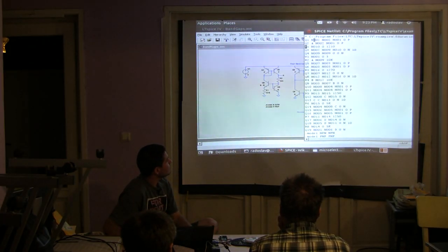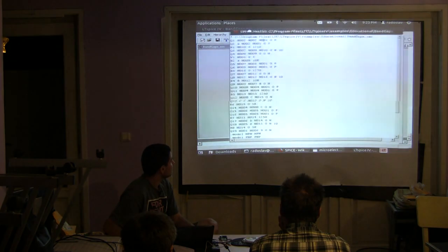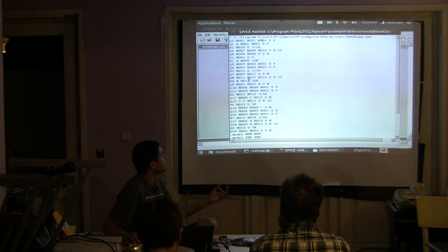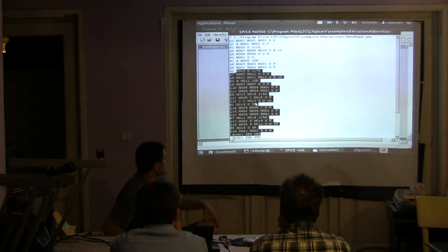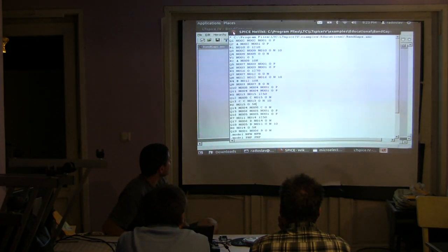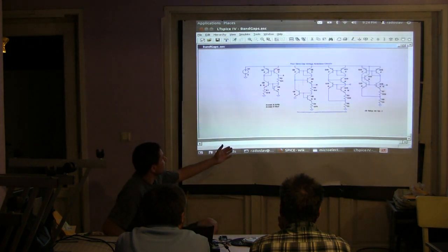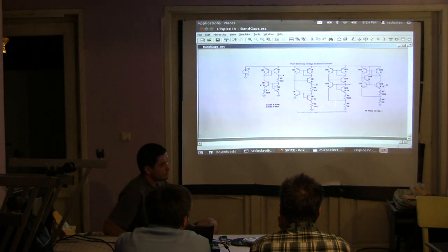Then you are placing the first node, second node, third node, and so on. It's actually a text file which you can modify. You can make your own circuits with such a netlist and simulate it without adding components in the schematic. You can use it as a background.